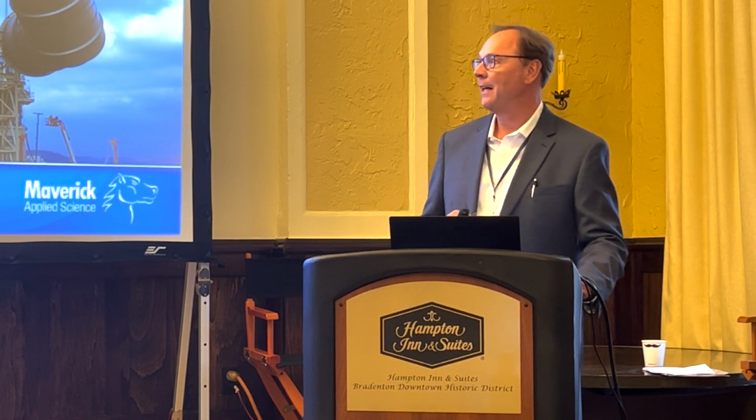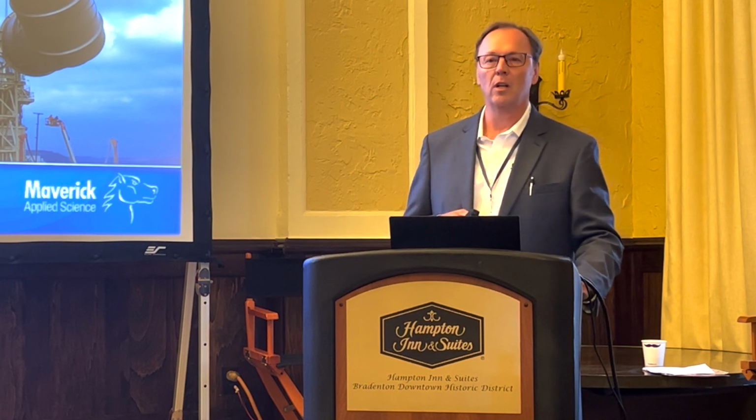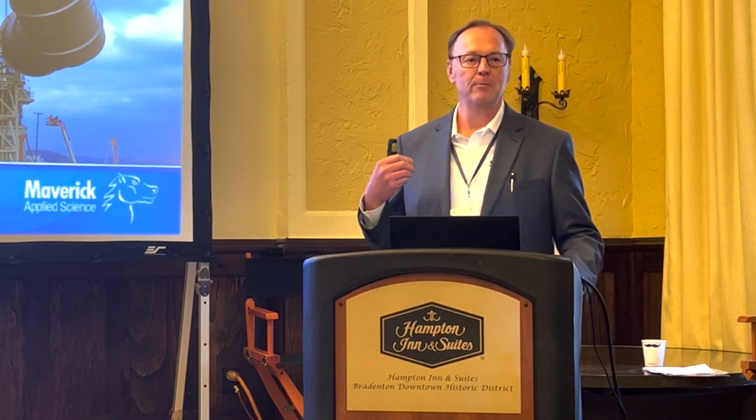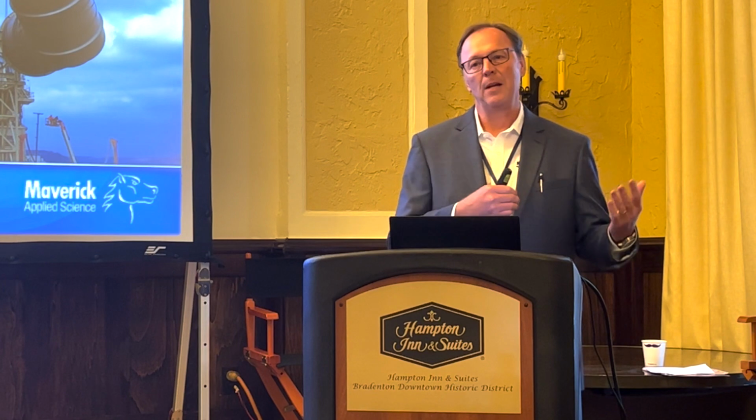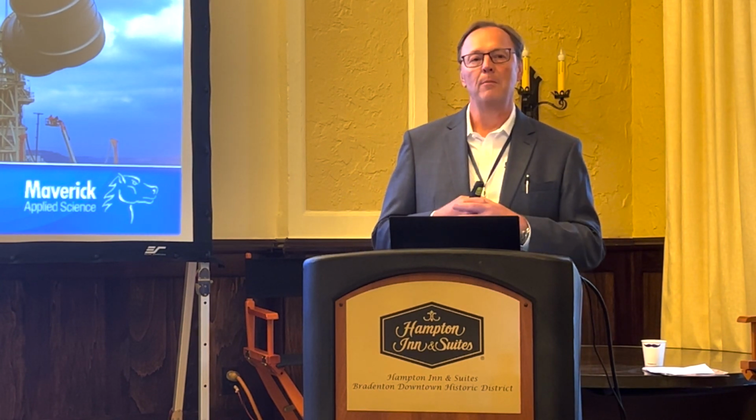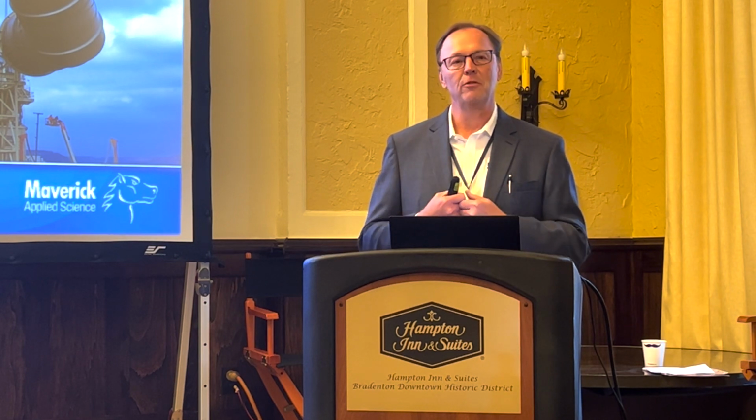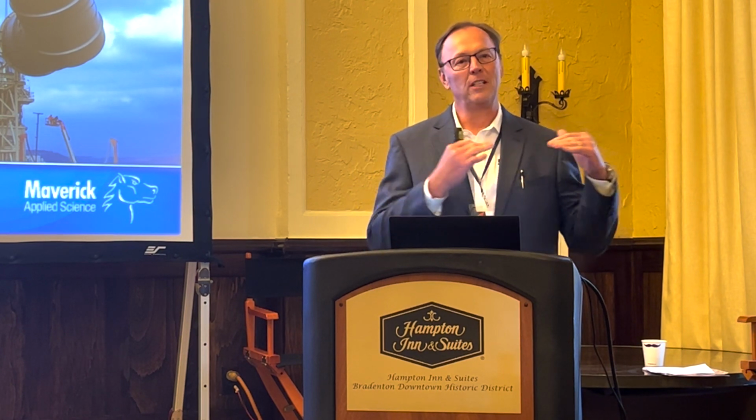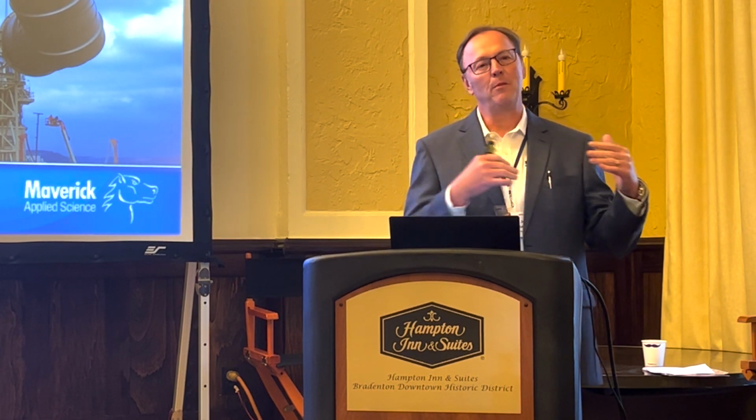So updated specs, and I want to qualify vendors. Some vendors are good at piping, others are good at tanks. There's a few that are good at both, but you want to know who's who. Everybody will say, yeah, we do that too. Usually when you hear that, that's not a good thing, because it takes a whole different set of tools to make pipe versus tanks.